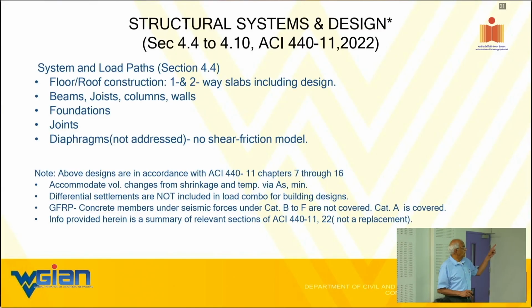All right, so the code is going to be talking about the loads and the load paths for different systems. Okay, I want to start from the bottom, not from the top. Diaphragms not addressed. What does that mean? What is a diaphragm anyway? A layer. It is a structural component that would help transfer load from one main component to the next main component, like a beam.